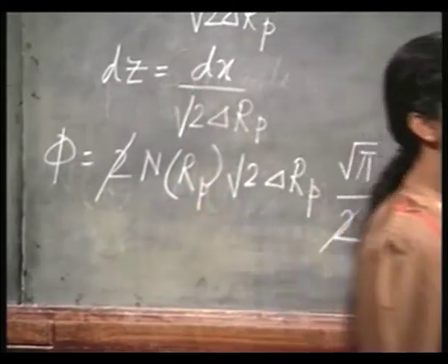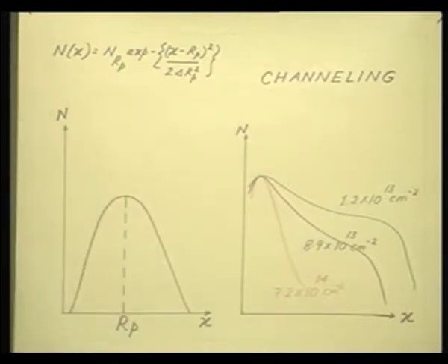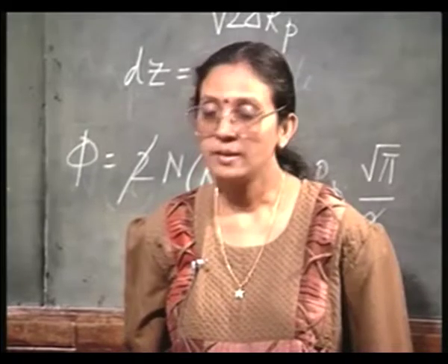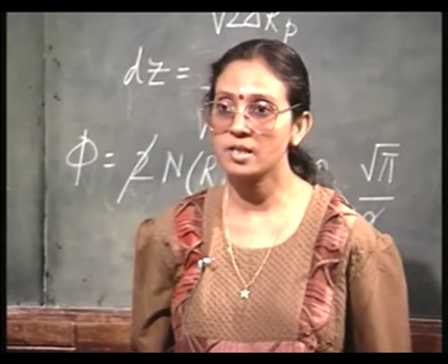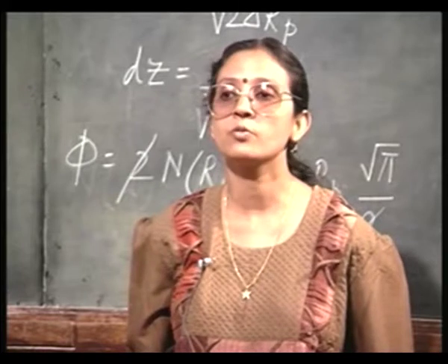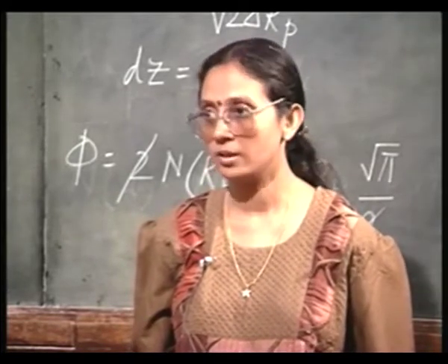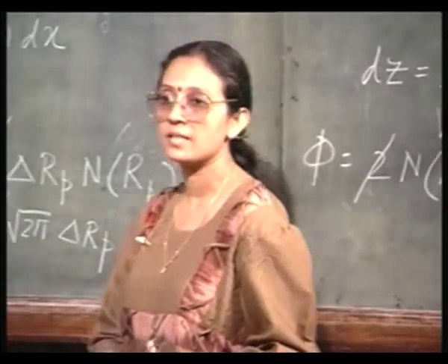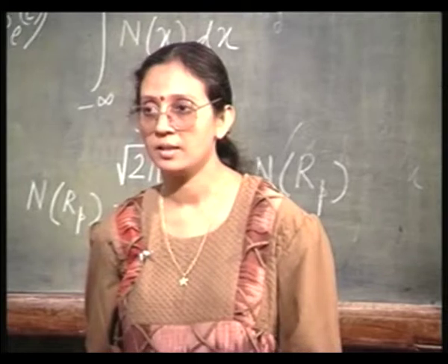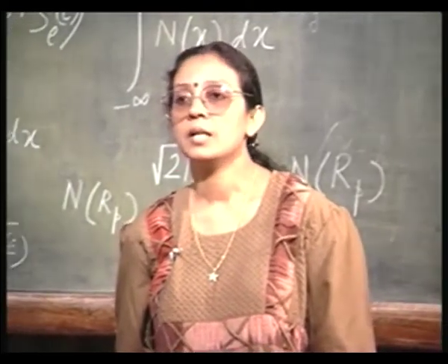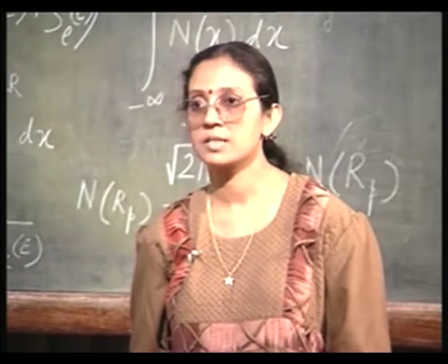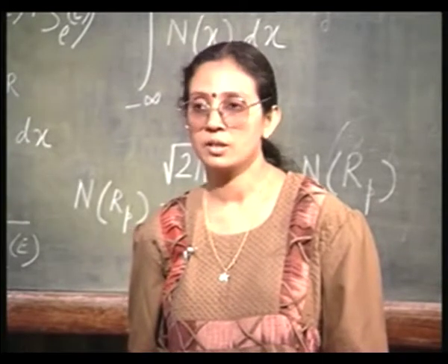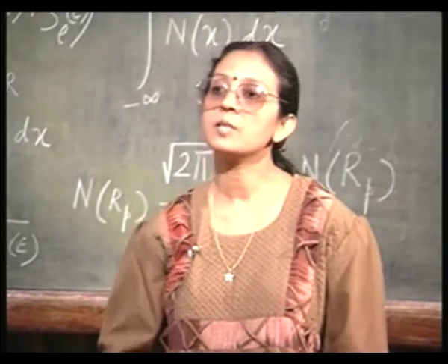On the other hand, when your dose is much smaller and the ion beam is directed along a major crystallographic axis, that is 110, then the disorder is less, the target resembles not an amorphous target but a crystalline target, and it is possible for the ion beams to find the channel and move forward through a much greater distance. So, you see, indirectly I have told you another way of making silicon surface resemble the amorphous target. That is, it is quite commonly done prior to the actual implantation itself. You do a self implantation, that is, you direct an energetic silicon beam onto the silicon surface.